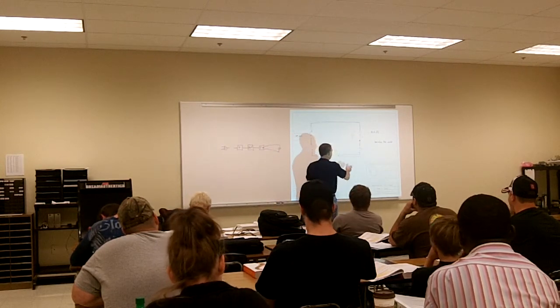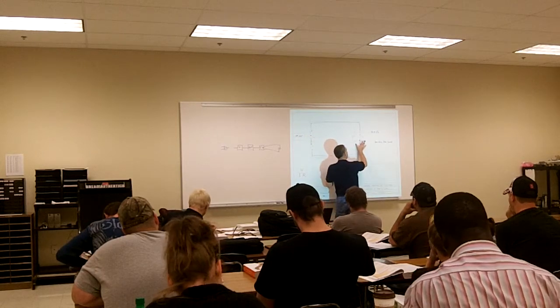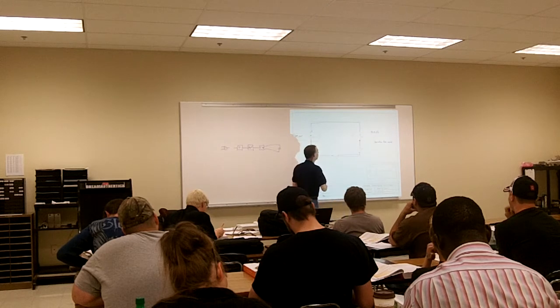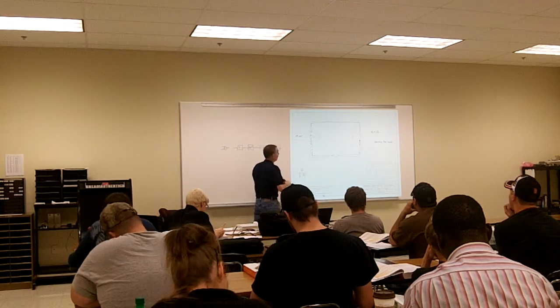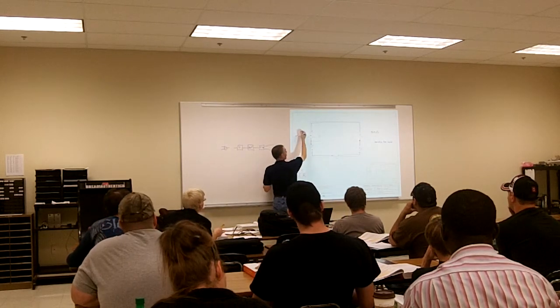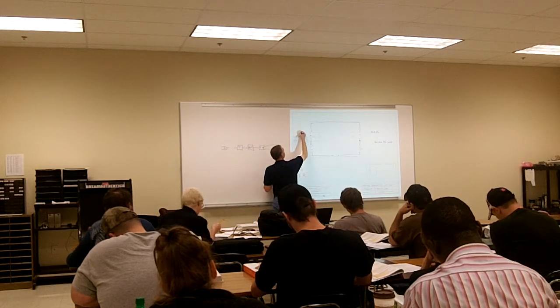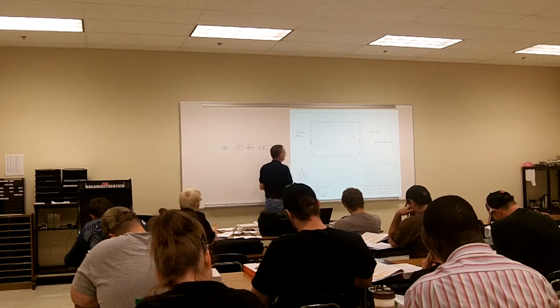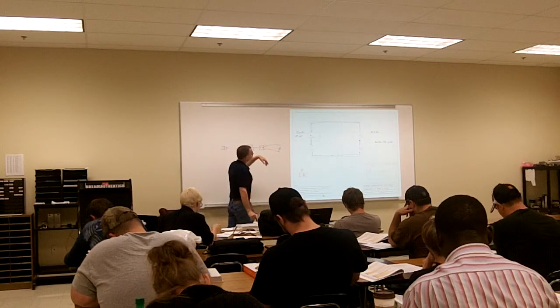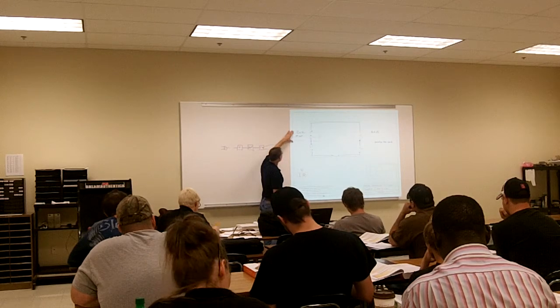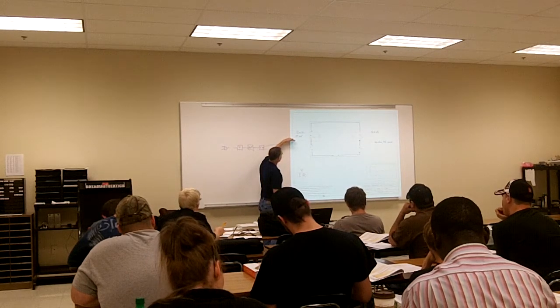With this being only a single resistor, my resistance total is just going to be the resistance of R1. So on these worksheets, just know that the resistance total is going to equal R1. So my RT is just going to be 120 ohms. Now I have two items, so now I can find the third item.